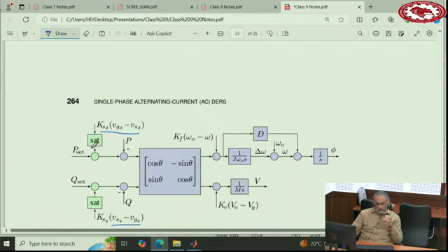By doing that, you are asking the converter to temporarily adjust its real power and reactive power to make sure that these two voltages go closer to each other. Whenever you want to connect to the grid, sometime before that, you enable this block, and the converter will push its voltage to become closer to the grid voltage, and when they are sufficiently close, you can close the switch.